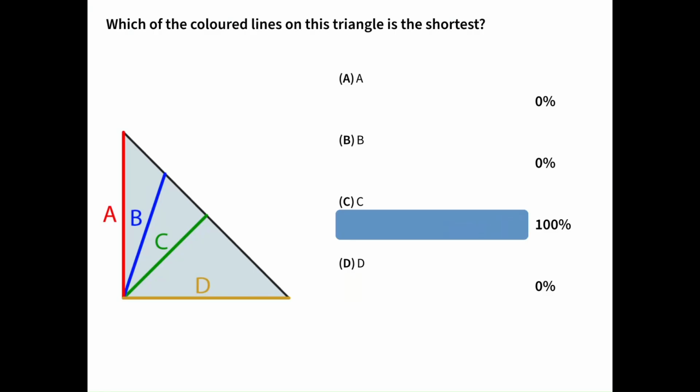Basically, what I'm going to be getting at here is the strength of the welds in terms of where the stresses are the highest. The stresses are going to be the highest where the area is the smallest. And for us, the effective area for our fillet welds is going to be through the line that's shortest, through the corner of the weld, into the free face of the weld.